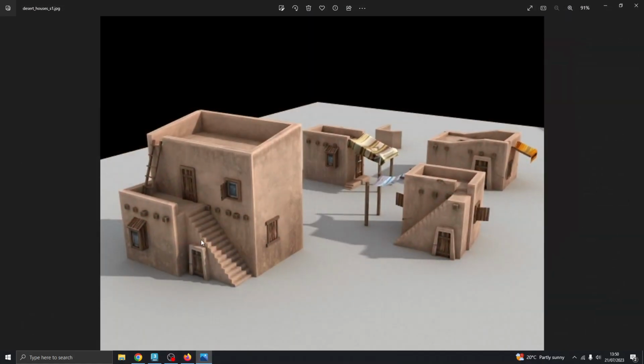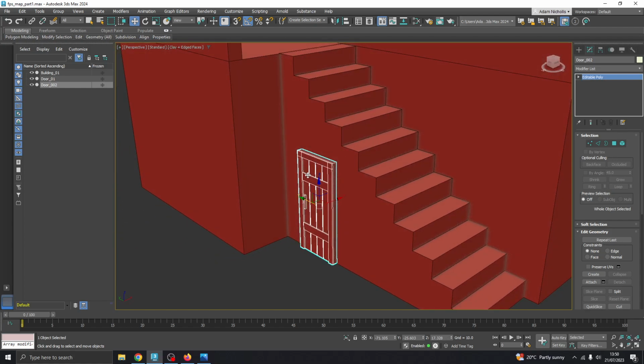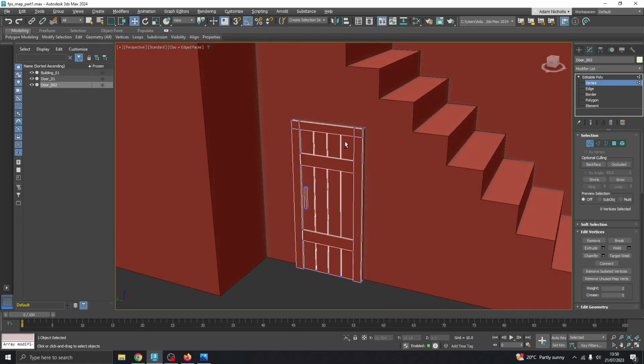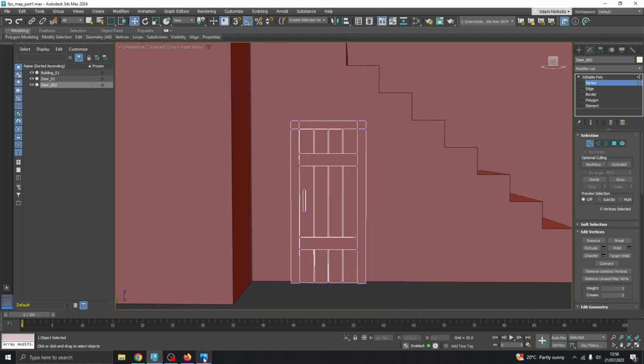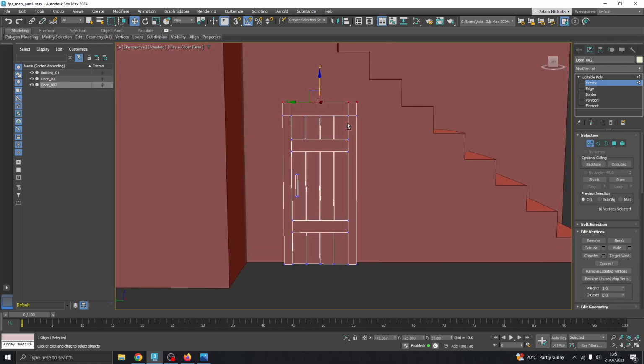Okay, so this frame comes out a lot further and it's kind of angled. So the first thing I'm going to think is, can I use what I already have? And the answer probably is yes. So if I go to vertices, what I can do is get all those top ones. So we marquee select all of them like that. So you select all those top vertices. We can just expand that size. Get the ones down this way. Expand that out that way. So just making this all a bit thicker.